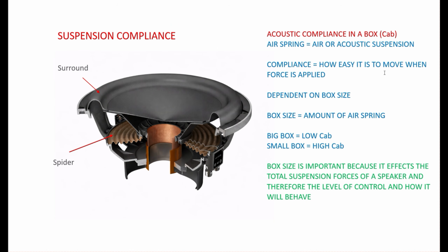And the thing about the air spring or the acoustic suspension is it is dependent on box size, right? So if you have a big box, there's much less air spring. If you have a small box, you have a high air spring, right? And that's important because it will affect the suspension of the speaker and therefore the level of control, and of course how the speaker will behave.